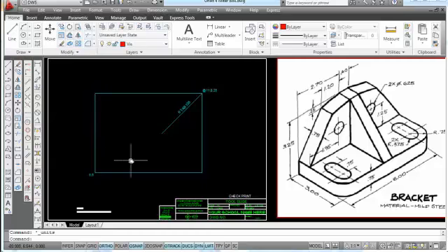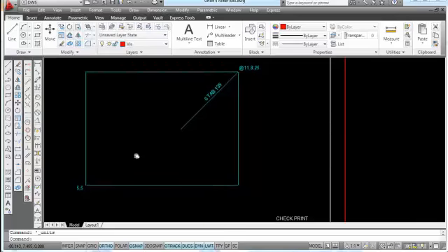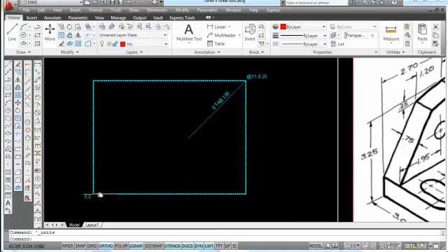which you're seeing over here on the left side of my screen. And what I did is I used the rectangle command, and I drew a rectangle that began at absolute coordinate 5,5 in the lower left hand corner, that went to a coordinate that was 11 units on the X and 8.25 on the Y. And then I drew a 45-degree line from that corner, and I drew the line about 6 units long, and I'll use that as the miter line.